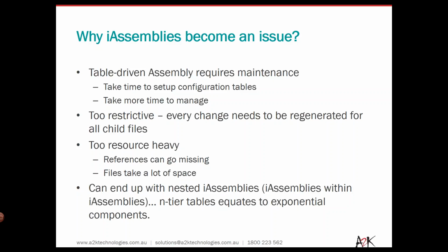This is because every time you create an iAssembly, that iAssembly points to a number of child parts or child subassemblies, so we have to generate parts each time. This can become too restrictive when each change you subsequently make to update these iAssemblies takes a bit of time to regenerate these child files, especially when you have nested iAssemblies within iAssemblies and so forth.